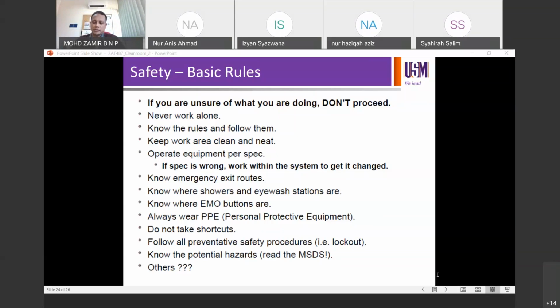So there was an incident in GF last time, Chartered Semiconductor in Singapore, where the engineers were doing maintenance on the equipment, and I think they forgot to enable the interlock. This is the interlock, it's not EMO. They forgot to enable the interlock. Then when you enable the interlock, the robot cannot run. When the robot doesn't run, you can do your maintenance on the robots.